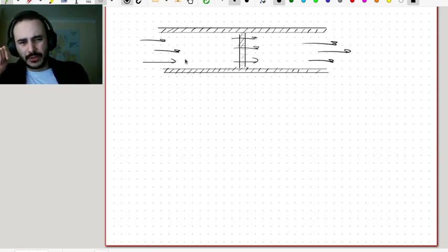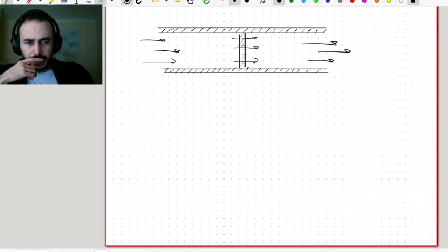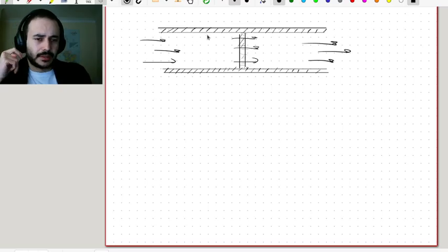Then we have to make a thermodynamic analysis of this situation, and imagine that you make a division, but this is a completely imaginary division for us to work with, and you single out a small parcel of gas to the left of the obstacle. This parcel has a certain volume, let's call it volume 1, and the gas inside of it has a certain internal energy, U1. And there is a certain mass of gas there, which we call M.